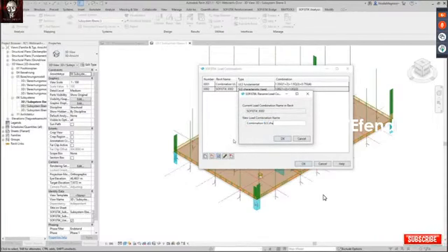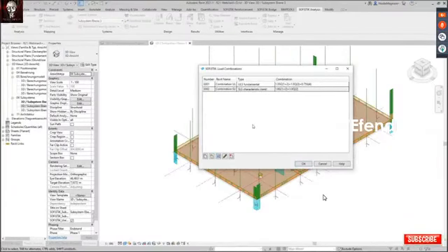And this load dialog allows you to define all the properties for the load combination, which you will need further in SOFiSTiK, especially the type, not only ULS and SLS, but also characteristic or fundamental or frequent is important in SOFiSTiK. And of course, this dialog allows you further functionality like duplicate, edit, or delete load combination.